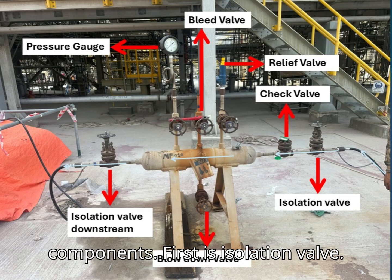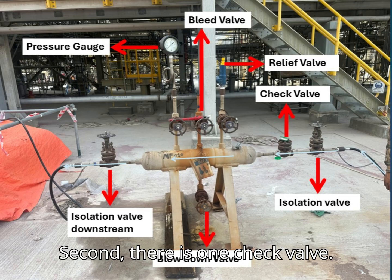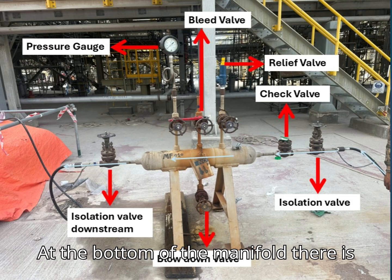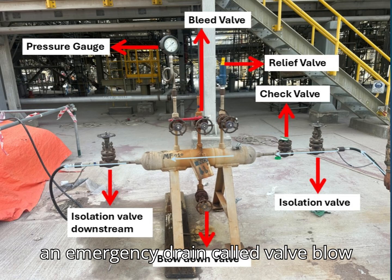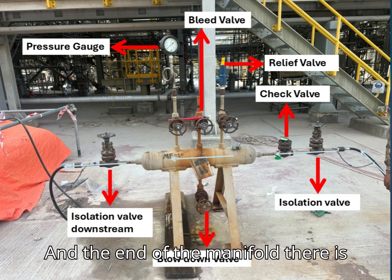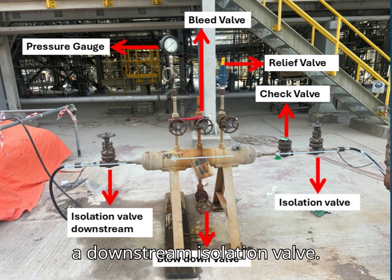First is the isolation valve. Second, there is one check valve. Then we have a relief valve. Then one bleed valve. Then one pressure gauge. At the bottom of the manifold, there is an emergency drain called the blowdown valve. At the end of the manifold, there is a downstream isolation valve.